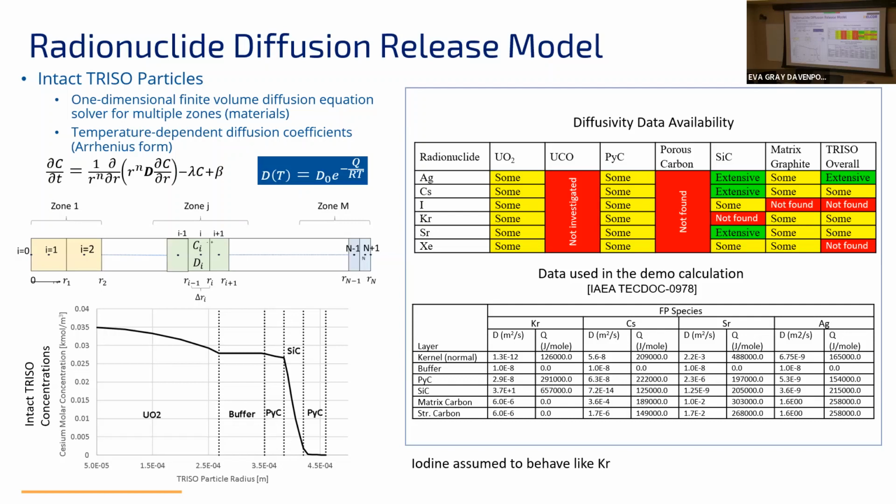Okay. For example, if we were to assume unirradiated conditions, very little escapes under steady state operation. It's kind of in the noise. When you're assuming very irradiated conditions, very damaged particles just sitting there releasing, we actually found over long operational time frames, and this is not reflective of the operational strategy or the actual fueling behavior, numbers on the order of 0.1% of your cesium inventory kind of popping out.